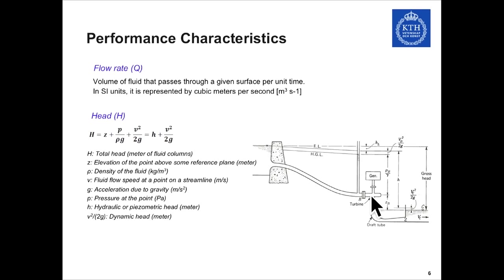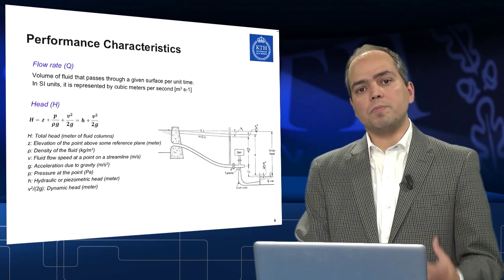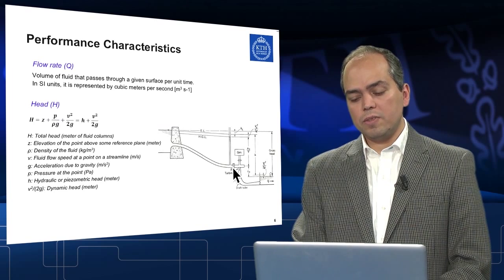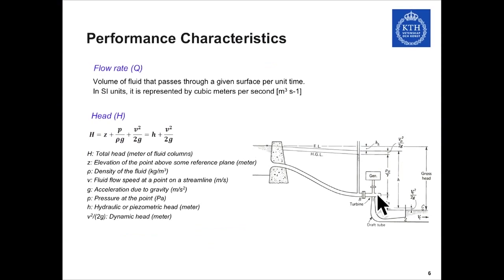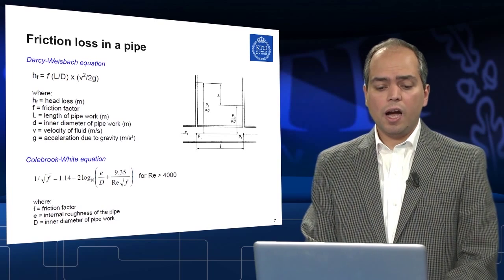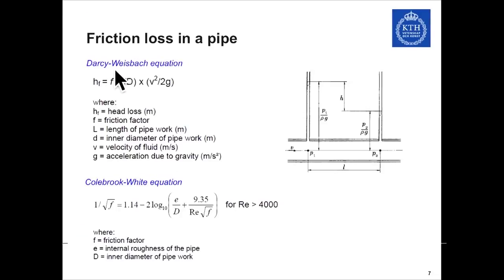In the previous equation that we've seen, that H, in order to calculate the power from hydropower, is in fact related to the head differences between the inlet and the tail level. In order to calculate the available head here, one should calculate the pressure losses in the system. And you've seen it before in the first series of lectures by Brijesh, how to calculate the head losses in your system, which is through the Darcy-Weisbach equation.